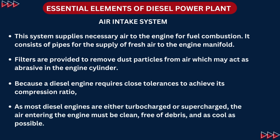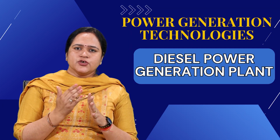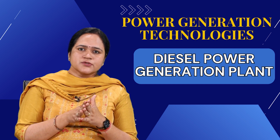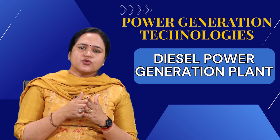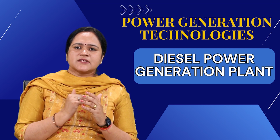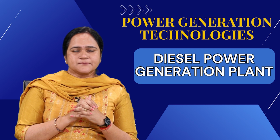As most diesel engines are either turbocharged or supercharged, the air that is entering from the intake manifold to the engine must be clean, free of debris, and as cool as possible. Sometimes we use the exhaust gases also so that NOx emission could be reduced, but at that time also two kinds of exhaust gas recirculation processes are there. So better is that cool air should be there.